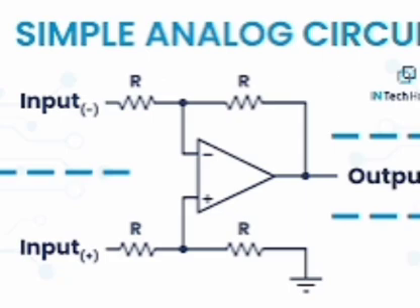Transistor biasing circuits. Bias stabilization. Stabilization is a process of making the Q point independent of changes in temperature and changes in transistor parameters. If IC naught, VBE and beta change simultaneously, then the net change in IC, delta IC, equals dou IC by dou IC naught delta IC naught plus dou IC by dou VBE delta VBE plus dou IC by dou beta delta beta, where dou IC by dou IC naught equals S, the current stability factor, dou IC by dou VBE equals S dash, the voltage stability factor, and dou IC by dou beta equals S double dash, the beta stability factor.